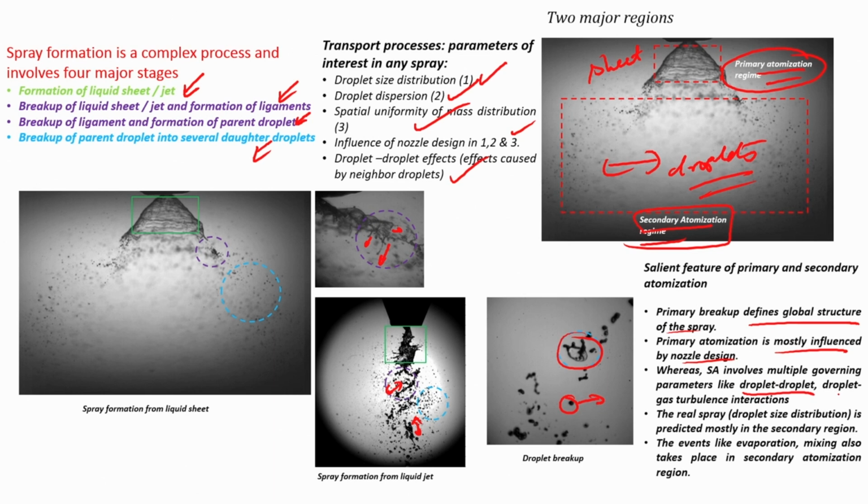These are droplets which interact with the flow field. This is a droplet, there is a high velocity flow over it, and this droplet deforms and breaks up. That will be like secondary atomization. Then these droplets will undergo evaporation, mixing, etc. Normally the atomization process is very fast, very quick compared to the evaporation process. So you can take that evaporation only starts to happen after the droplets have substantially reduced in size. There is evaporation that continues to happen always, but if you talk about the dominance of the scales, atomization happens at a much earlier time.